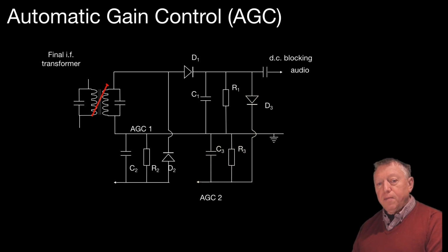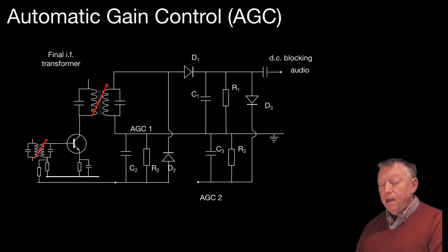Let's pull things together a little bit. There's our circuitry, and here we're adding in an IF amplifier. You can see that was an example, I think, from receiver C, where we looked at the circuitry within the blocks, and that was an IF amplifier. You can see the highlighted red AGC control line there, going back and affecting the base bias of that NPN transistor, and therefore the gain. So that covers AGC, I think, certainly to the extent required by the RSGB Advanced Certificate.